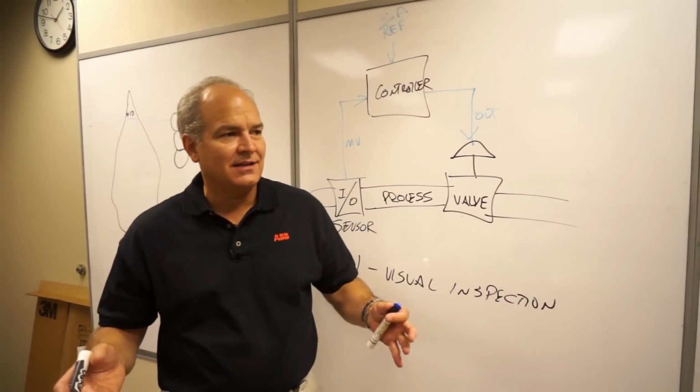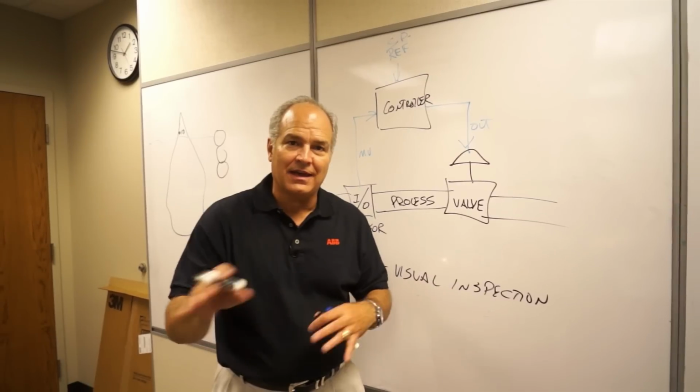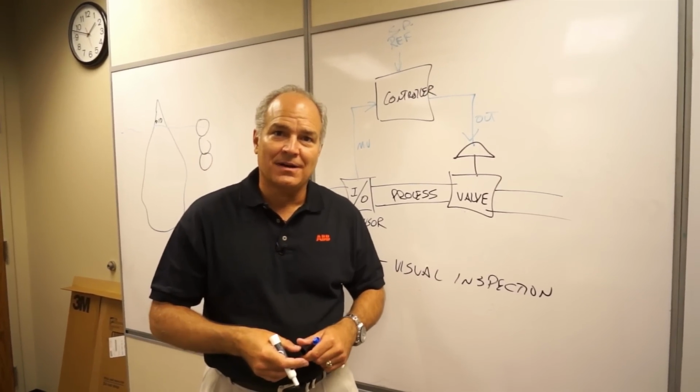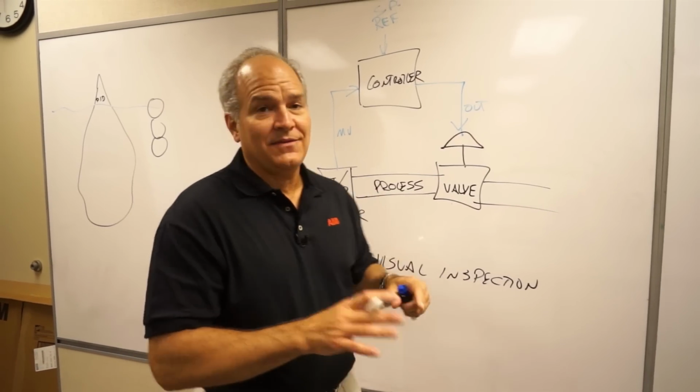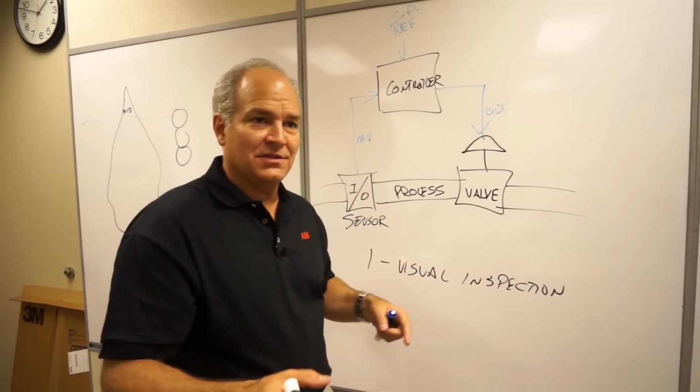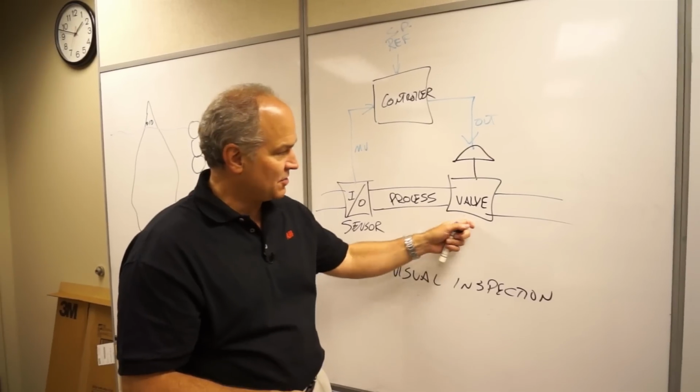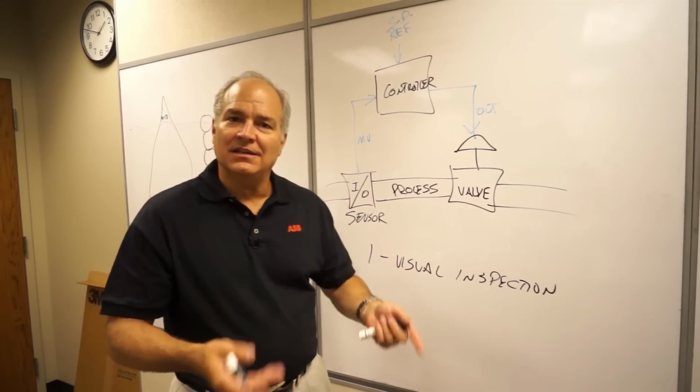I was at one site and they said, can you tune this loop? I said, well, I need to go look at it. And they're like, this guy's going to fix our problem. And they're like, why is that? I said, because you're the first one to ask to go out and see it. So if it's safe, go out and have the operations or whoever the operators are take you and show you the valve.